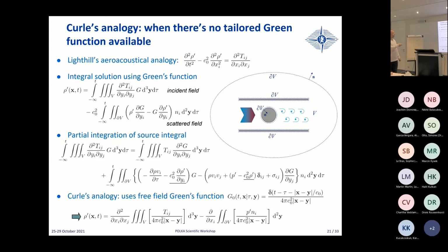So you have something that looks like the Reynolds stresses that you have to integrate, and then you have a scattering integral. So it means that these sources have to be reflected by the boundaries in order to leave the domain. You have your Reynolds stress, and the sound is reflected by the cylinder, reflected by the duct, and eventually leaves the domain to radiate to the small guy here, in the circle.